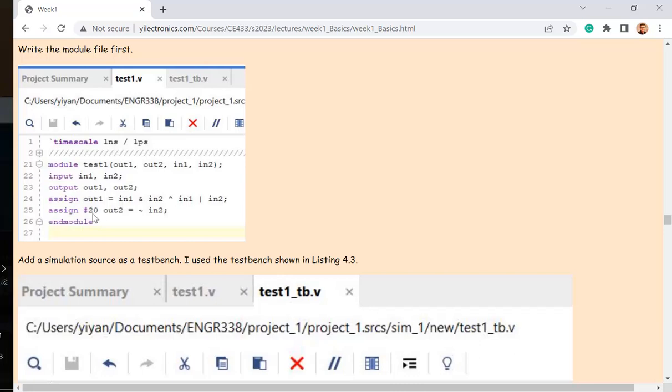I don't think this is synthesizable, which means you can run this kind of example in simulation on Vivado, but when you have a time delay like that, you will not be able to implement it on FPGA. Which means you cannot synthesize it to a certain thing physically inside the chip. So this is just for simulation purposes, just to let you know.